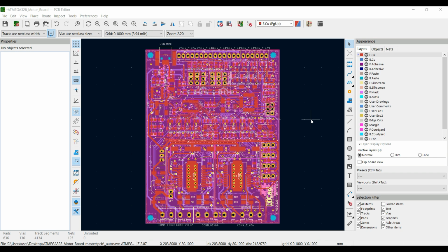So what the manufacturer will do is either hand solder all these components or use a machine to place components on the PCB and then solder them. For the machine to stuff all the components on your PCB, the manufacturer will ask you for a file that is called the component placement file. This file includes data about which type of component will be placed at which place on your PCB.